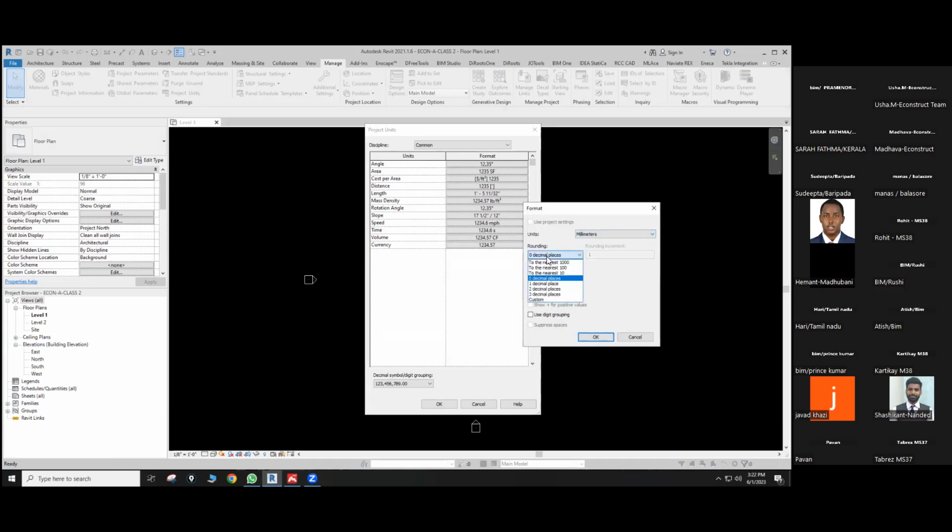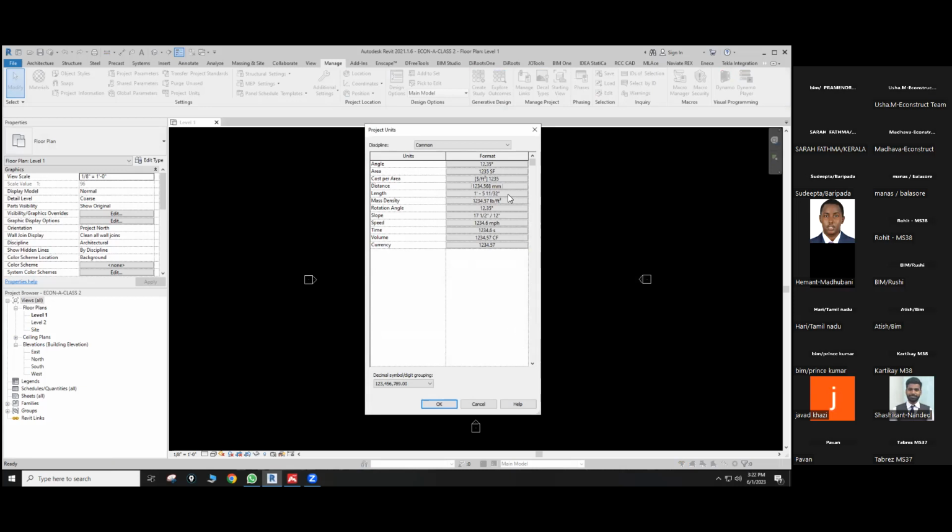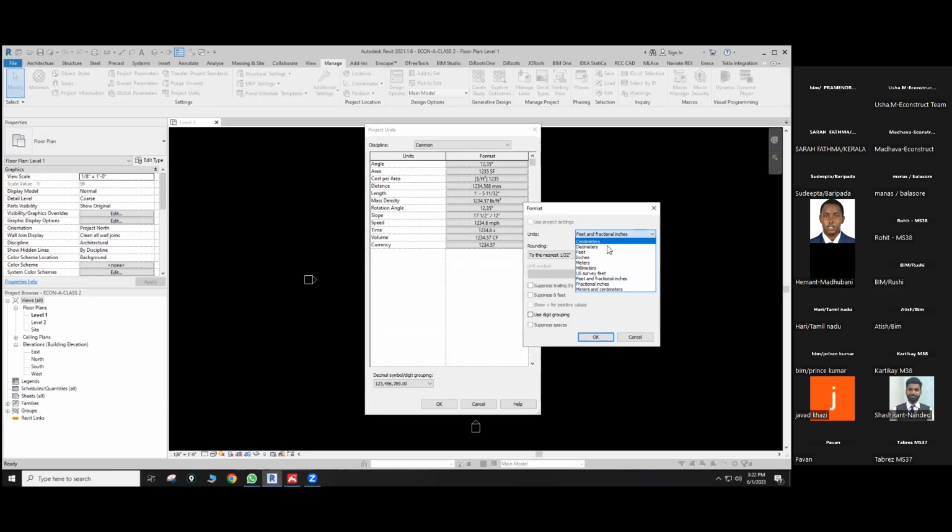millimeter. So decimal, I'm going to keep it at 3 decimals actually. So which is the mm. Okay, done. So the distance is done. And the length, I'm going to keep it the millimeter. So there are 3 decimals. Basically in mm, we use 3 decimals. In centimeter, go for 2, and meter, go for 2 normally. So why do we need to decrease the precision decimal places? In the meter, don't keep it greater than 2 decimals precision, because sometimes when we do some design modeling, don't care about that.